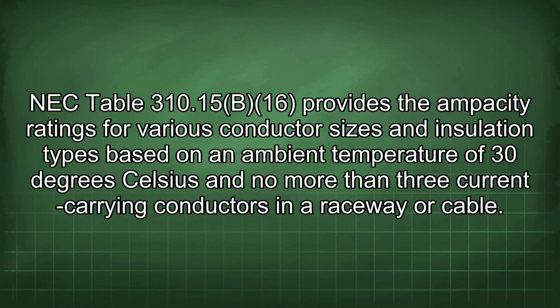NEC Table 310.15(B)(16) provides the ampacity ratings for various conductor sizes and insulation types based on an ambient temperature of 30 degrees Celsius and no more than 3 current-carrying conductors in a raceway or cable.